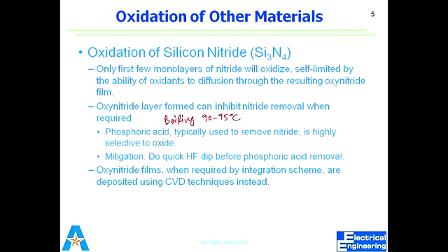So can we, in general, think of oxynitride as an oxide in most of its properties? Oxynitride is actually when you have silicon nitride on top of the silicon wafer, and you put it in at high temperature in an oxidizing ambient.